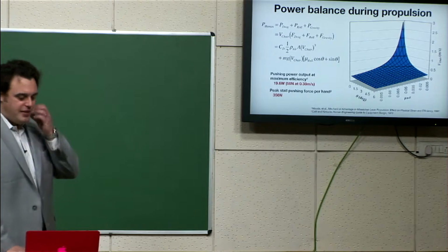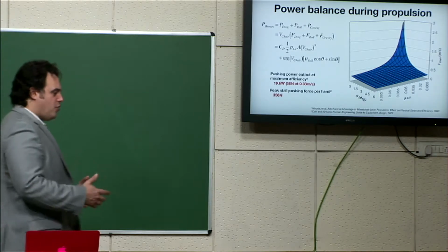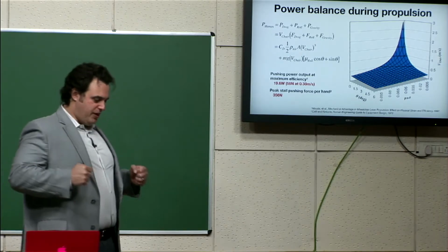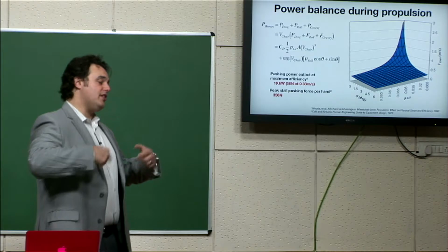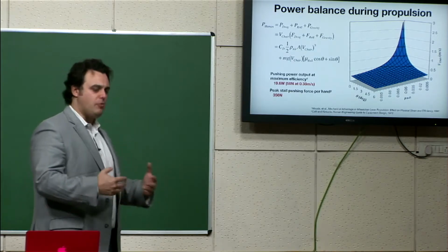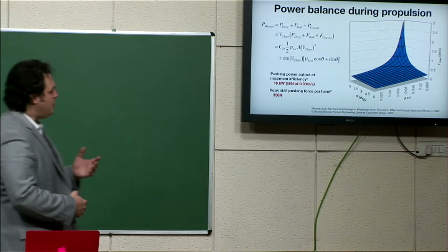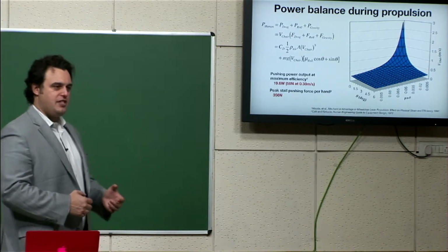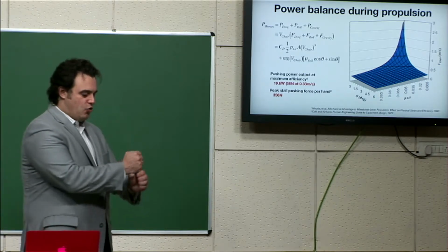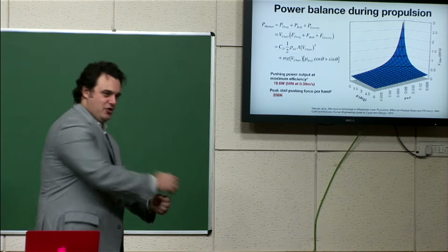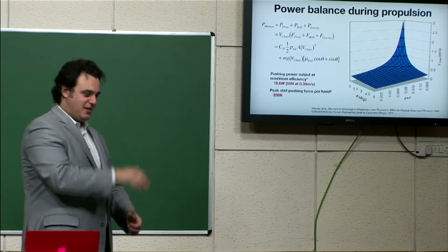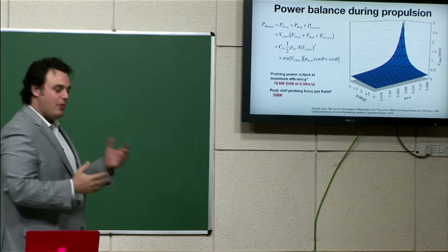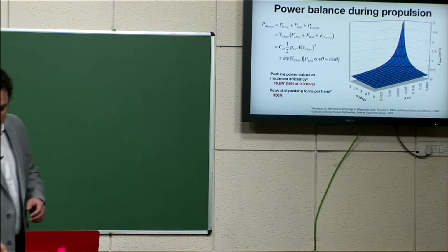The other factor we had to think about was if we get into a really tough situation with tougher terrain, how much force could we push out, like doing a bench press, in order to produce a lot of torque to get through sand or mud? And what we actually ended up using as a benchmark of pushing force was US Air Force data from pilots who had to grab a stick and push it to control the rudder or the elevators. So it was a very similar motion of going on a lever, right? So it was a reasonable ballpark estimate that we could use in our calculations.